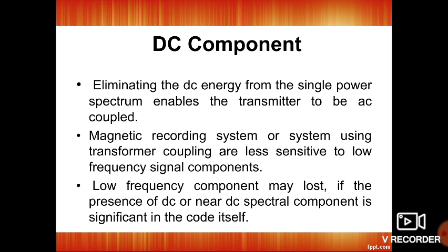In analog waveforms, the waveforms are converted to digital signals by pulse code modulation, delta modulation, adaptive delta modulation, differential pulse code modulation, etc. By such techniques, the analog waveform can be converted to digital signals. This digital data can be represented in different forms of waves. These waveforms are commonly known as digital data formats. Their representations are called line coding.